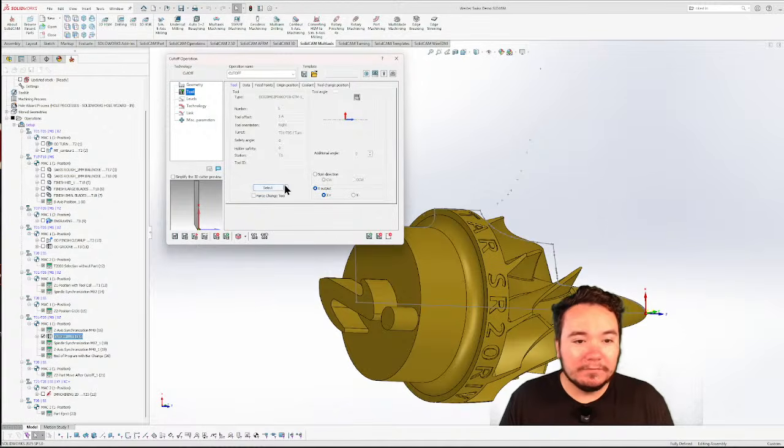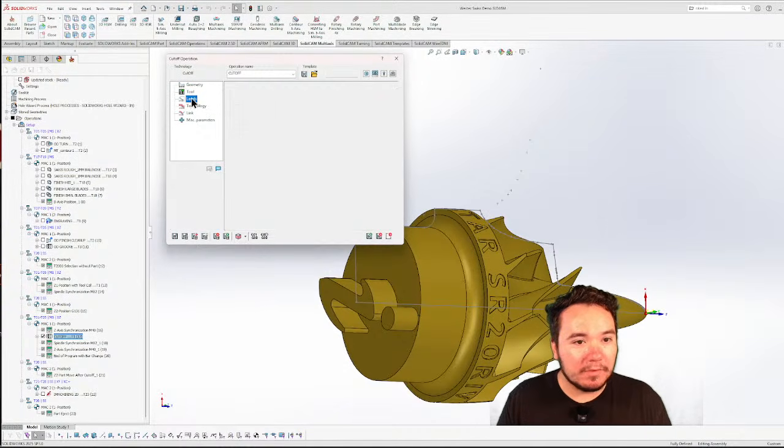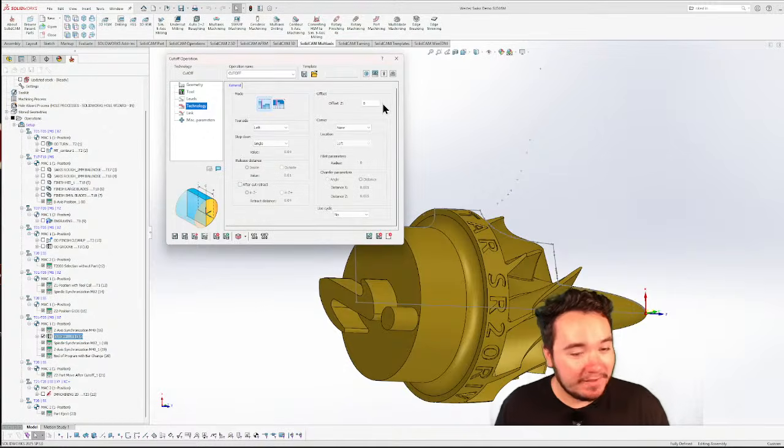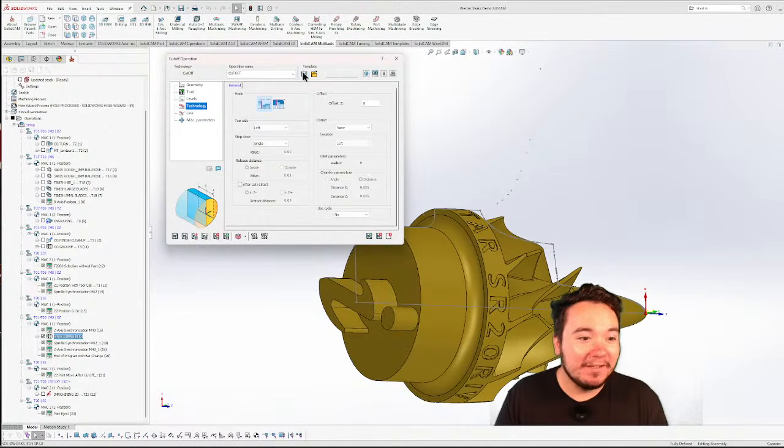Grab our tool, pretty easy. Tool number 1. Tool side is important if you want to offset. If you're going to face on the sub, we're not. It's brass. The face looks pretty good, just with the cutoff, just making sure that the feed rate's good.